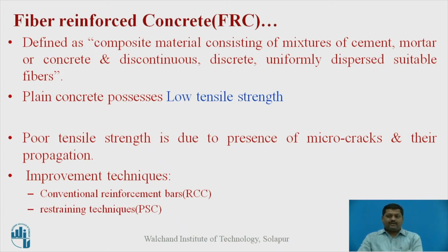Now, what is the need of this type of concrete? Our plain concrete possesses very low tensile strength. Low tensile strength means if any tensile stresses occur in the concrete, it will probably be subjected to cracks. These cracks will widen, and the reason for low tensile strength is the micro cracks. The presence of micro cracks and their propagation will reduce the tensile strength.